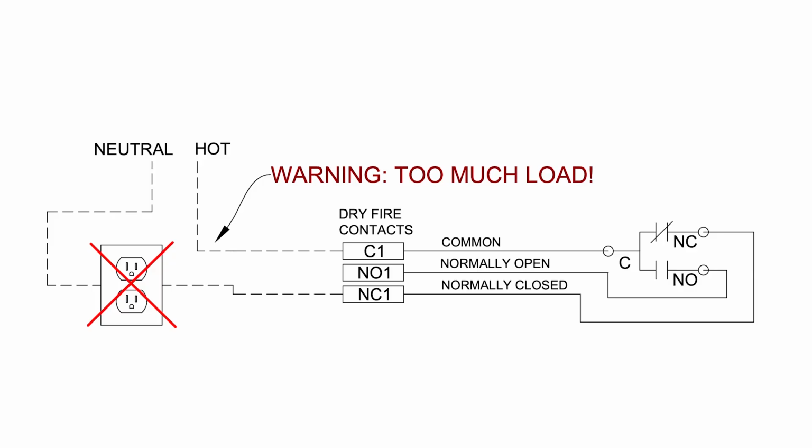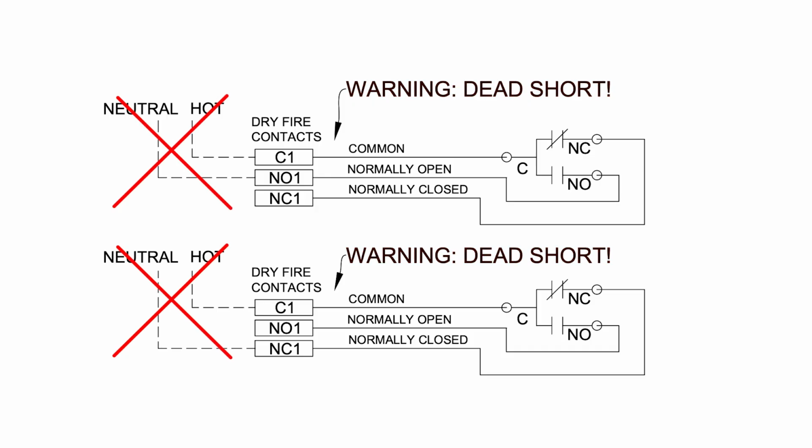Do not bring outlet or appliance power straight through the contacts. Do not wire both coil voltage hot and neutral to the contacts, as this will short the relay.